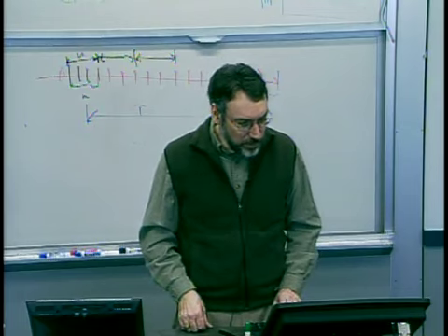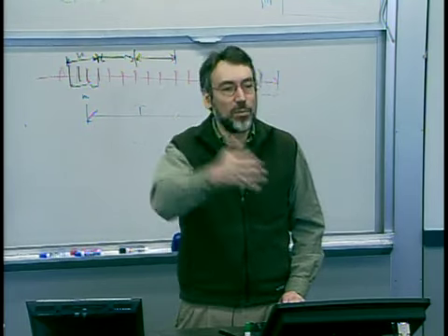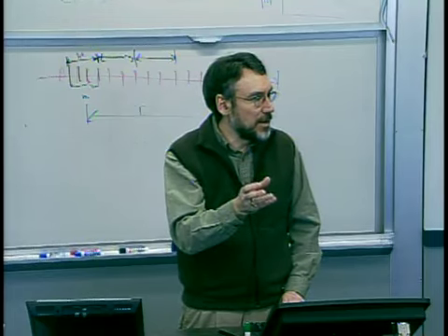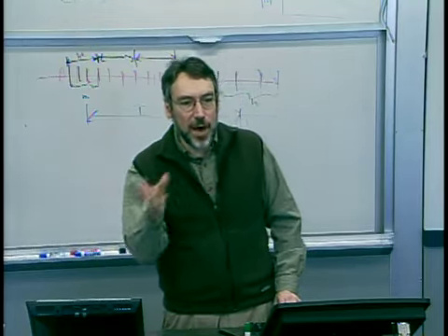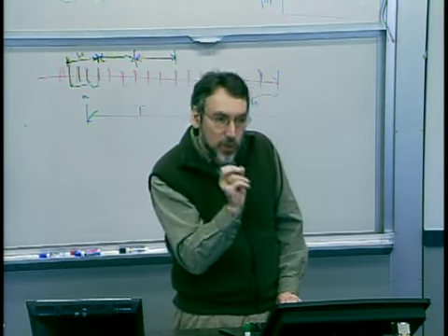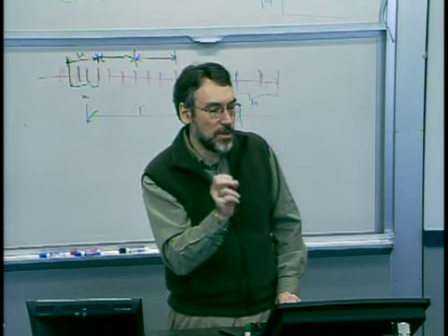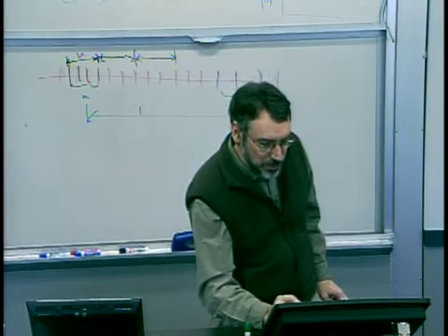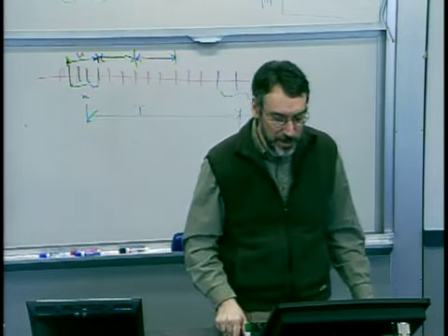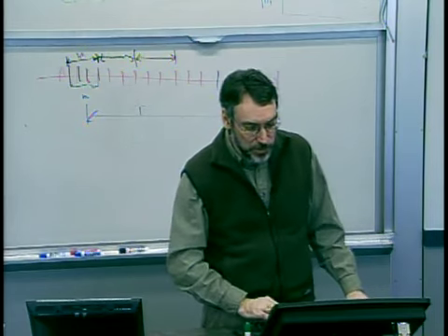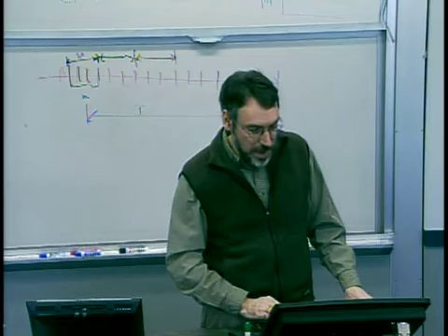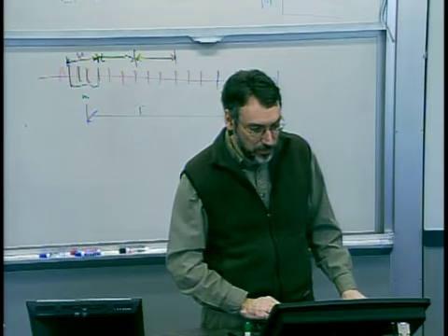And the reason really is so that you are robust to small mean shifts. Even if you've got that small mistargeting, you've still got enough room in an inherent process with, say, a CP of 2 or a CPK of 2, to be able to have a very small number of non-conforming parts.